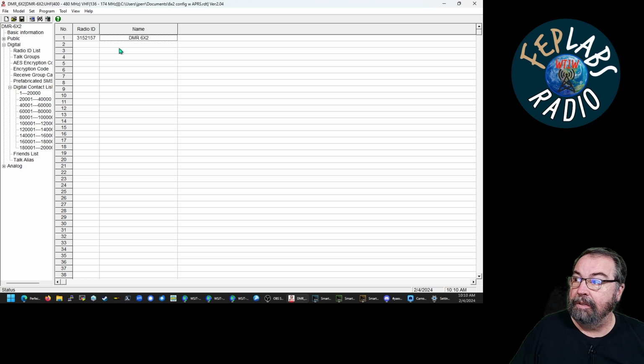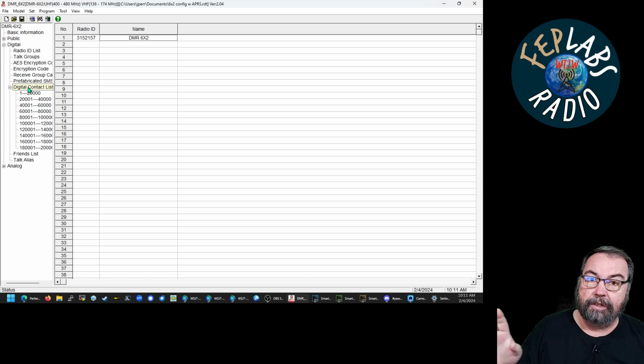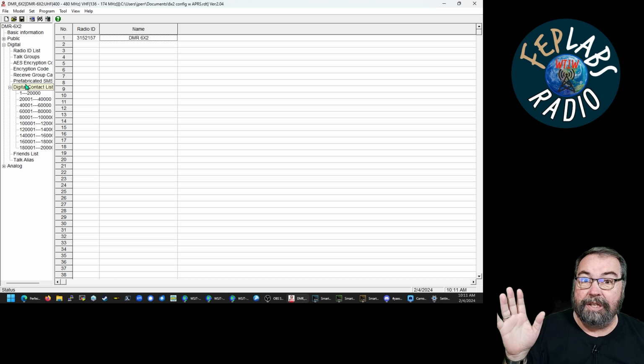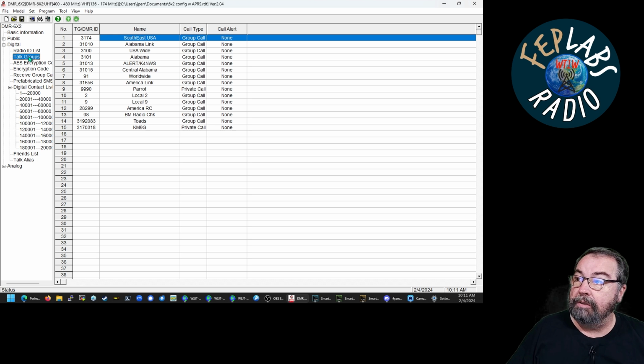Step 1 is finished. The next thing you've got to put in is your talk groups. Now, depending on your CPS, this may be called talk groups, it may be called digital contacts. This particular CPS has digital contacts, which we're going to talk about at the end of the video. It's basically the same stuff. These are all private calls, individual hams and their DMR IDs. This is a completely optional thing for any of these radios. You don't have to have this in there. Again, we'll talk about that a little more later. So right now we want to put in our digital talk groups.